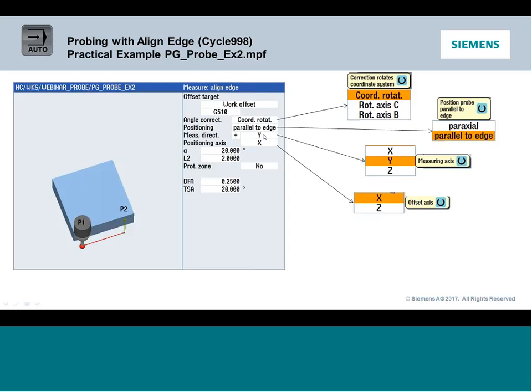Then you're going to tell it what the measuring direction is and an axis, as well as the positioning axis. That means I'm physically moving the probe in the Y to take the measurement, but then when I've got to move over, in this case to the right, to the next move, that's going to be my positioning axis right here. That is basically everything else that we filled out. It's pretty much the same.